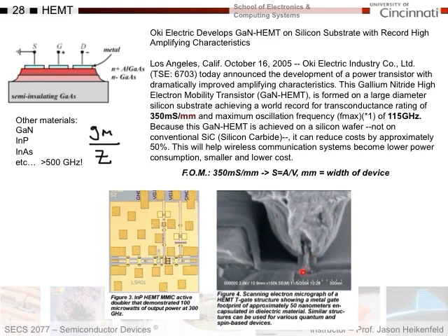So again, they can reduce the gate capacitance and reduce the channel resistance such that in a circuit like this, they get a small RC time constant. So it's all about making the transistor smaller if you want faster switching speed. In fact, I think they say here, a metal gate footprint of approximately 50 nanometers is what they have there.